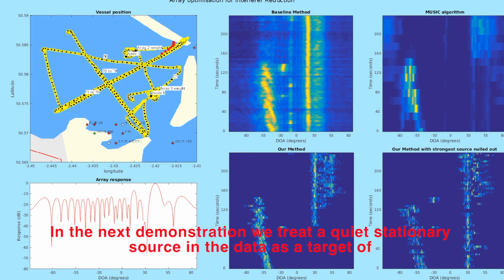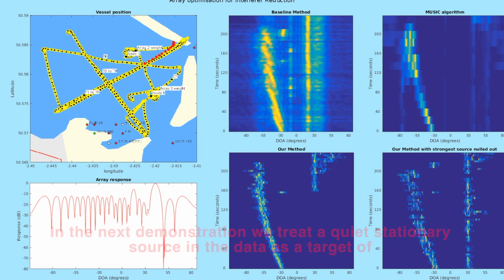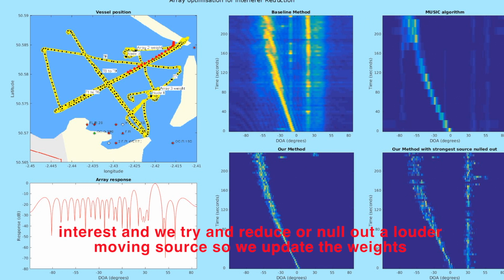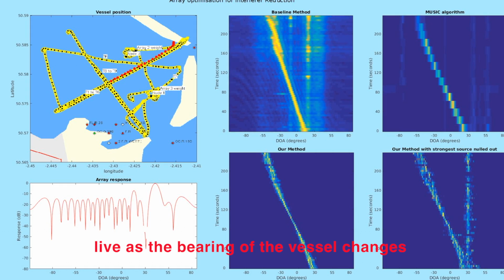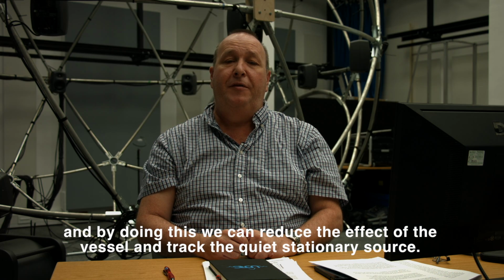In the next demonstration, we treat a quiet stationary source in the data as a target of interest, and we try and reduce or null out a louder moving source. So we update the weights live as the bearing of the vessel changes, and by doing this we can reduce the effect of the vessel and track the quiet stationary source.